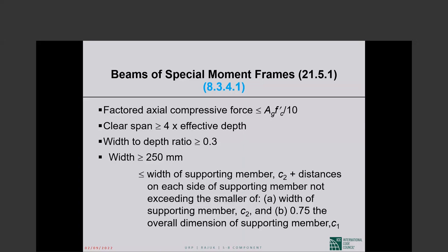And this is again covered, but I think you can give a short reply. In addition to the provision of ACI 21.13.6, I repeat, ACI 21.13.6 is for SDC D, E, or F, but you mentioned that it is for IMF. Are there any reasons? Also, slabs without beams is not permitted in SDC D. Then why does ACI 21.13.6 refer to this under SDC D?